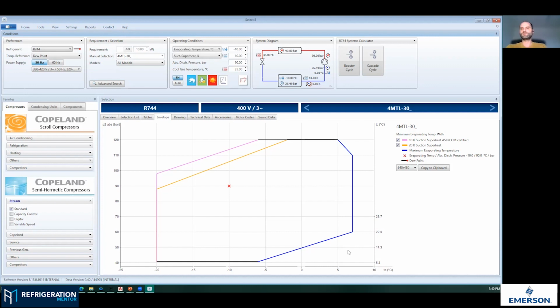Because of the too big mass flow, which is causing too big pressure drop on that component, for example, the suction screen. So I also did see in some extreme conditions that the suction screens were broken because of this effect of too big mass flow in the suction. Wow. So this is like your maximum evaporator temperature, just way too high.